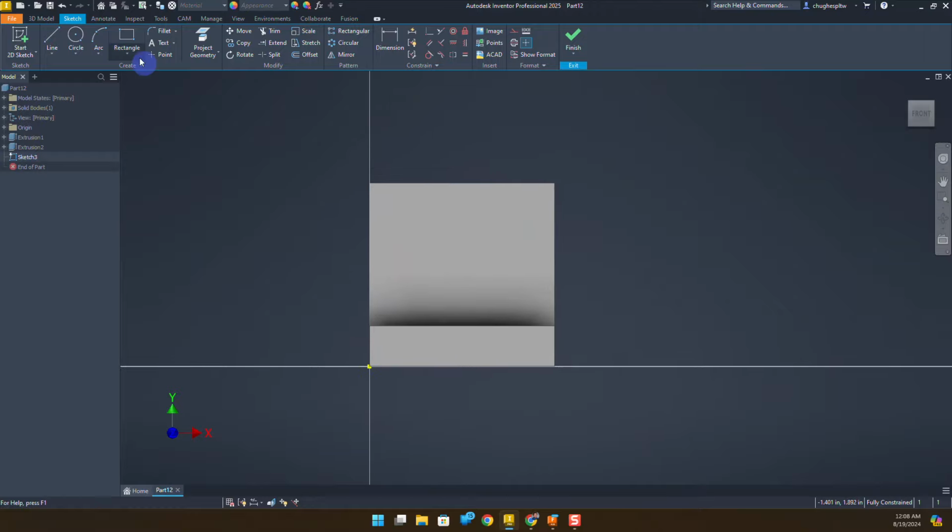And what we're going to do is draw a 2-point rectangle. So I'm going to go right off the top of the ledge here. I'm going to draw it about the size and the shape. Again, it's staying off of this midpoint that we have. Okay, in order to do that, I'm going to select the dimension tool. From this left edge to the left edge of the opening, it's going to be 0.375.